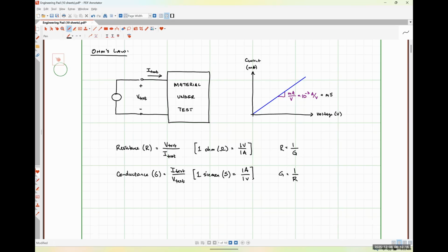So other than today, we're really not going to deal with conductances at all in this class, okay? So I would highly encourage you guys that whenever you're given a conductance, like in your homework sets for today, maybe the ICA for today, although it's not particularly necessary, you simply just take the reciprocal of it so that you can treat it like a resistor, because you know loosely how resistors behave, and we'll get into more of that in a little bit, and then just go on about your day.